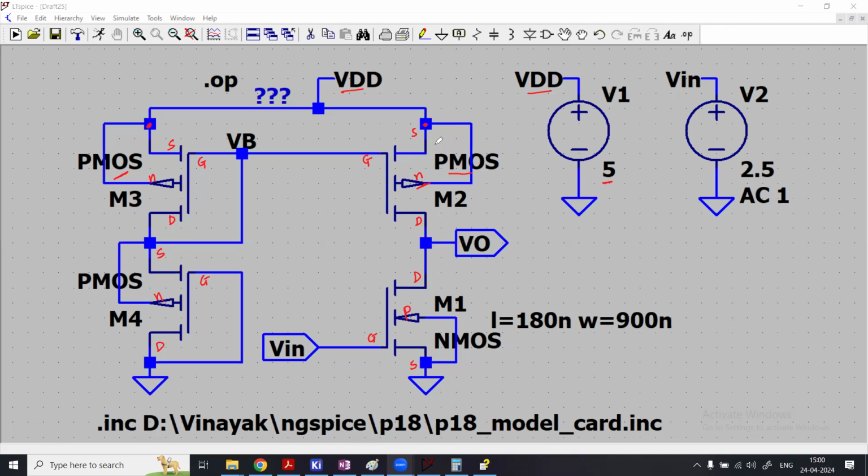However, you see that this transistor, M2, acts as an active load for M1. So there is a diode connected load, an active load, or in the simplest form, you can use a resistive load for the NMOS circuit. So you have Vin here and you have this resistive load. This resistor can be replaced by a diode connected MOSFET or the active load, which is shown.